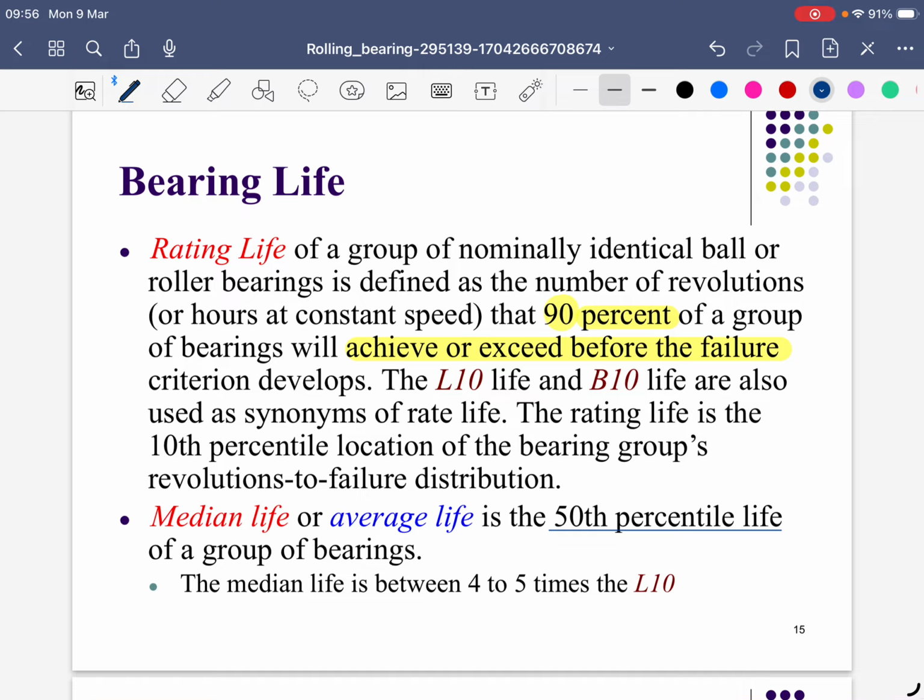So the formula provides us the standard for L10. But if you want to use this one for longer life, you can reduce the size of the bearing by yourself, and use the calculation formula to determine for L50. So you take one bearing that can have a life longer, 4 to 5 times, but the possibility that this bearing will be damaged is more.